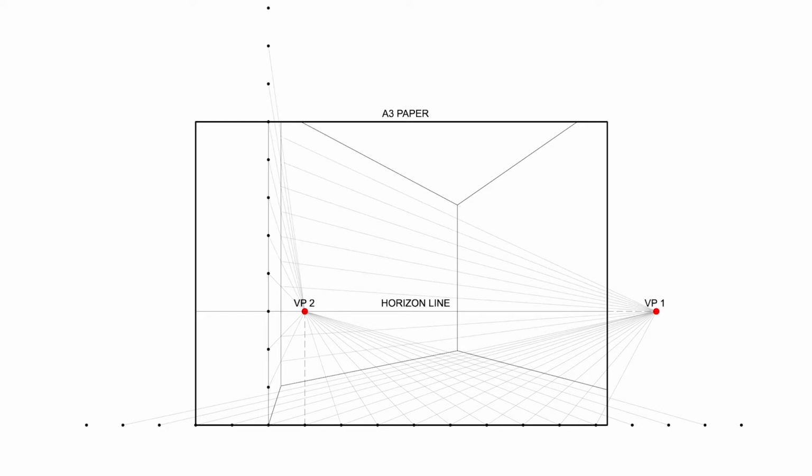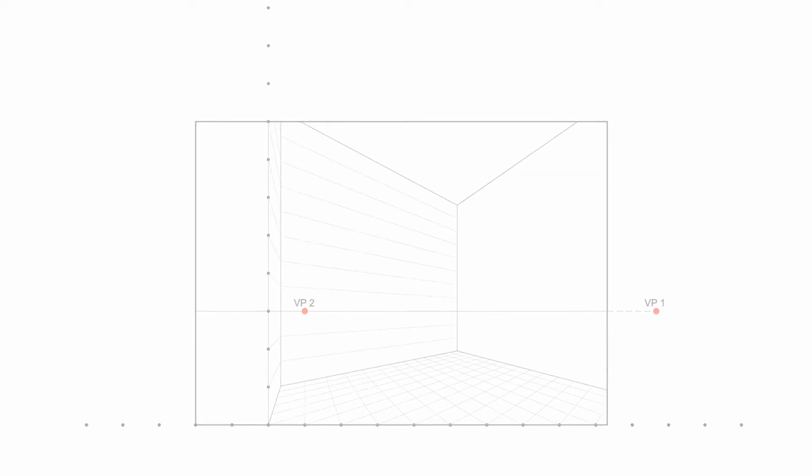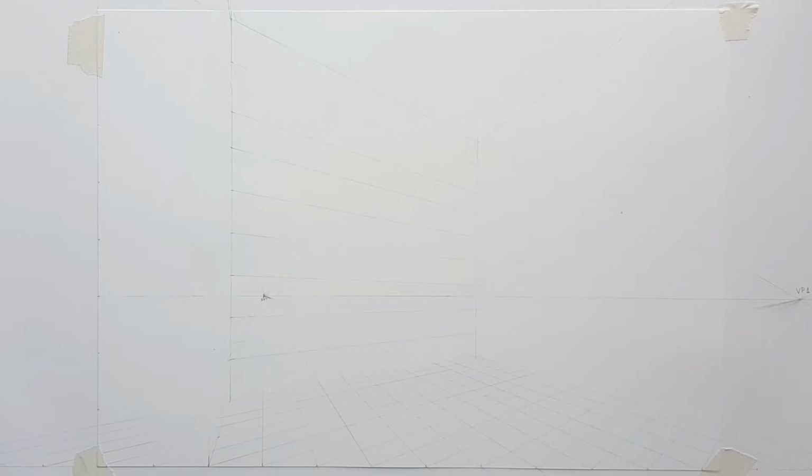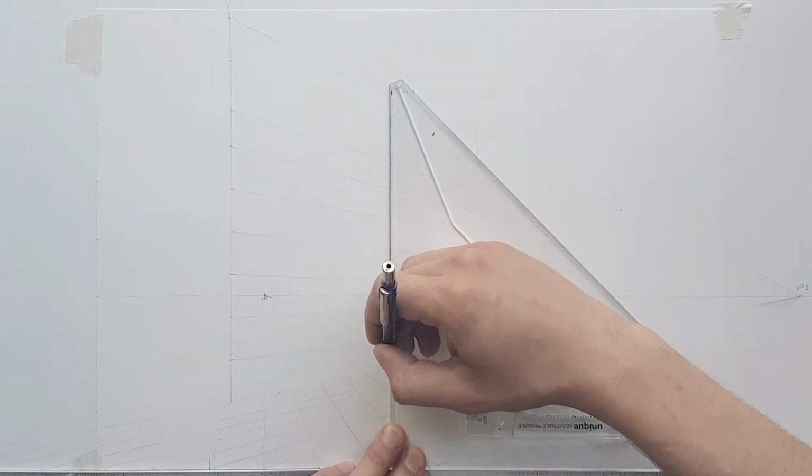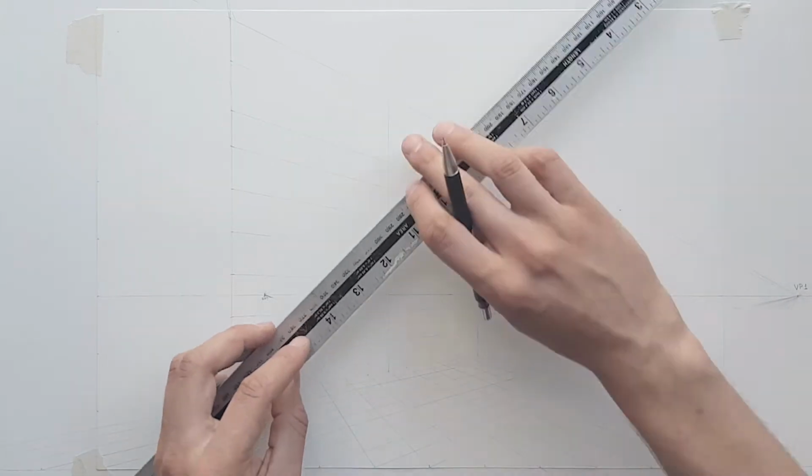Similarly, we're going to divide the back wall into half a meter increments. Once we have that, we can start putting windows on the back wall. These are going to be arched industrial type windows, pretty common in the old factories, especially in the UK.